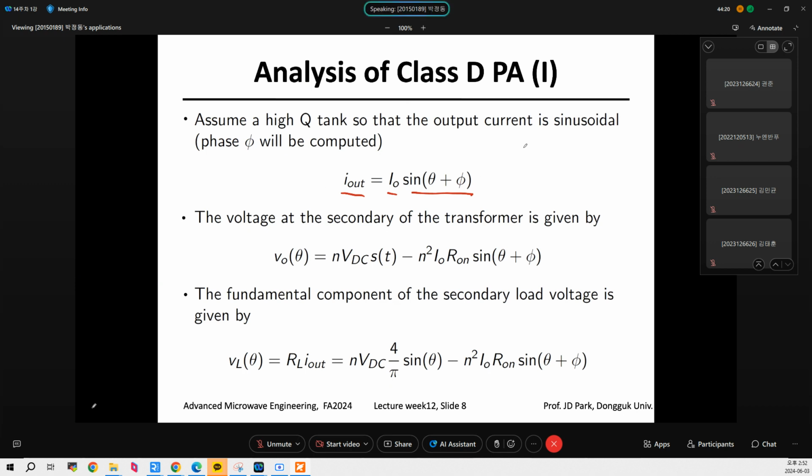As you remember, here is a transformer, and there is another transformer over here, with a resistor, which is the class-E amplifier. So the transformer is 1 to N, and the voltage at the secondary of the transformer is scaled up by N times.